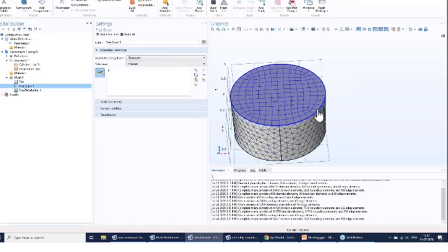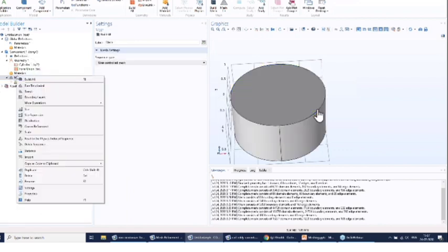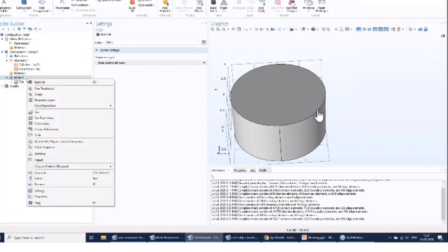Now some people are having some difficulty in applying those options, so I will again repeat it. You can right click on mesh. You can also clear, first of all, clear your mesh completely. You can clear by selecting this delete sequence. Using this, you can clear your mesh.